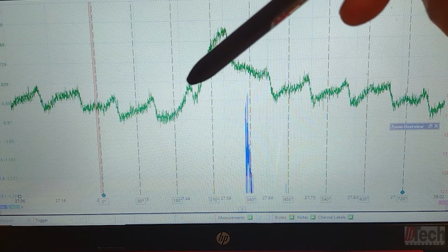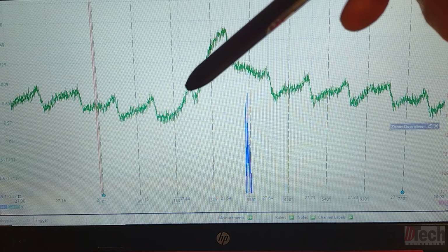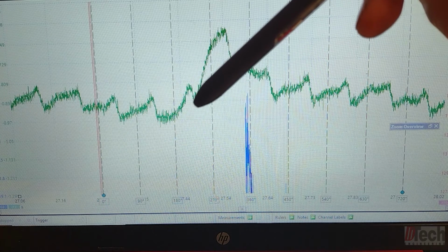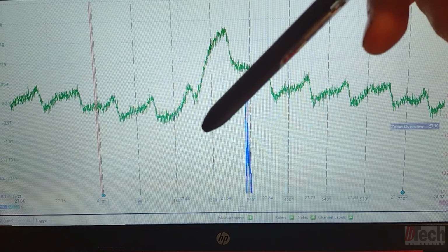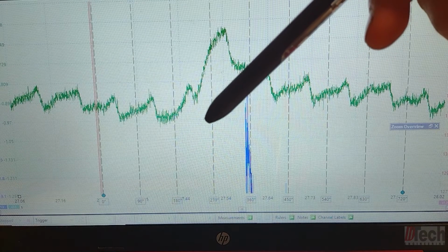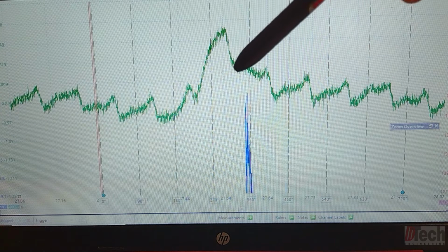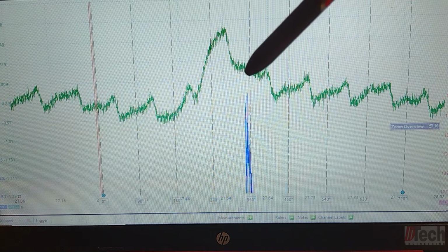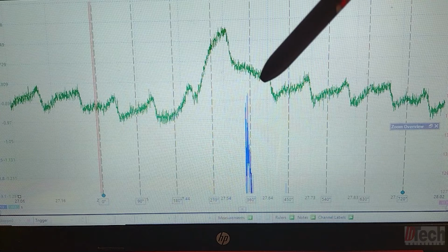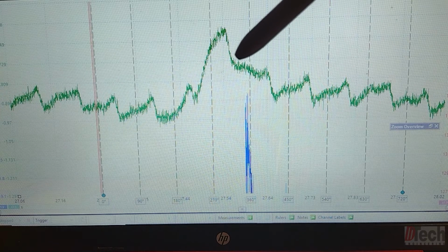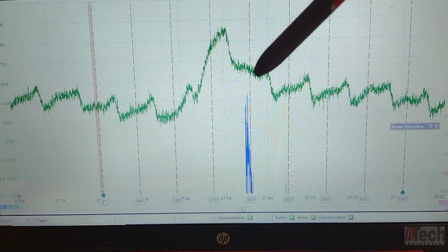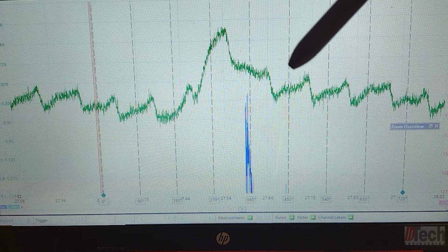So you're seeing a cutoff of intake pull due to positive pressure being introduced by compression, leak down, bleed off through the intake valve from cylinder 8. And then in the trace, you're watching the engine slow down in speed due to fighting compression and the higher amperage draw. Then you can see that here on the intake trace.